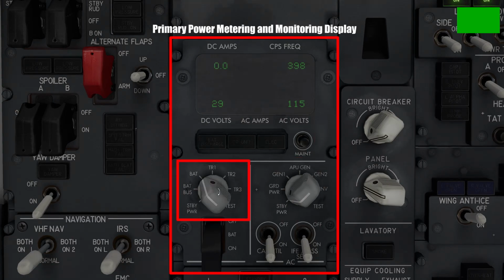Coming down, this left knob allows the pilot to specifically see the power draw from various different selected systems in the aircraft using direct current. Notice how the numbers on the display change when I go from the power being supplied by the onboard battery to the various other electrical systems in the aircraft. The same is true for the right knob, but for monitoring AC power instead of DC power.